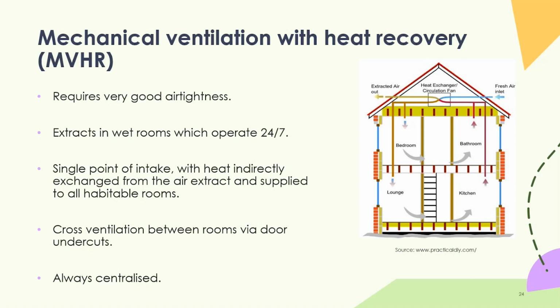And the typical air tightness that you need to be aiming at is about 3 cubic meters per hour at 50 pascals pressure. That's if you were running a pressure test on the house. That would describe a level of air leakage, and you need to be at that level or lower, really, to be able to use an MVHR system properly.